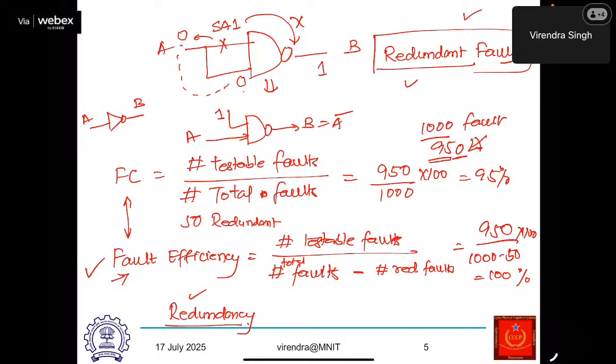However, most of the algorithms which are based on some heuristics work reasonably well because there are multiple test vectors for a given fault. And when you start to generate, you are likely to generate one of the many test vectors very quickly. And that's how test generation became a practical problem, and we are able to do that.